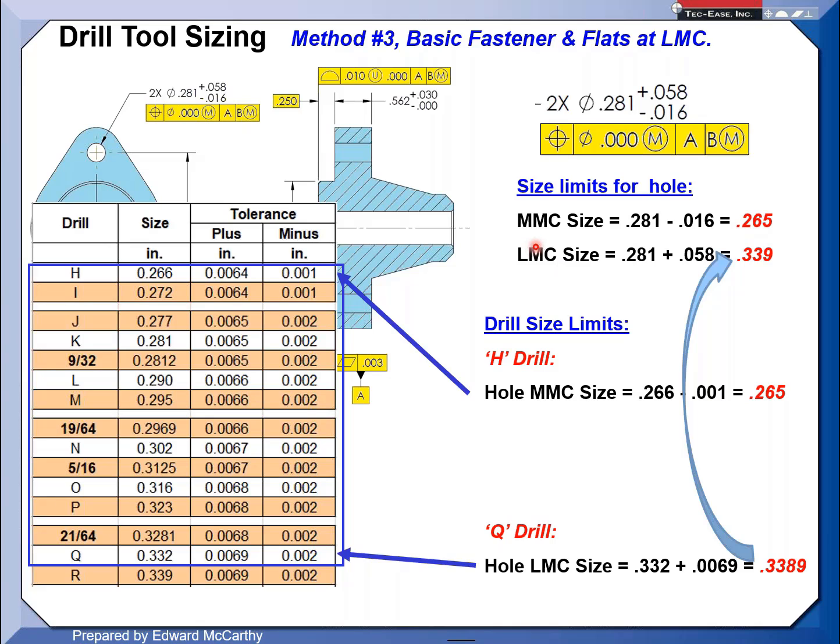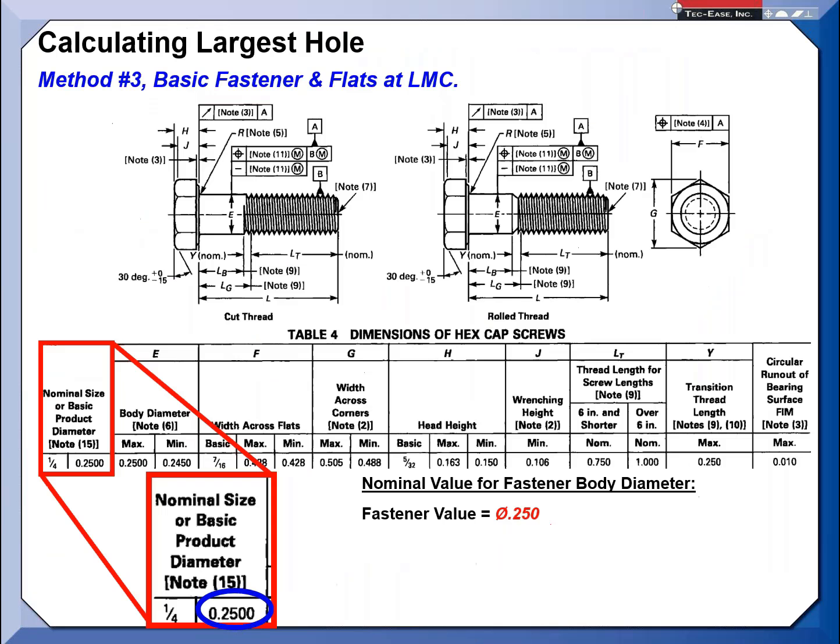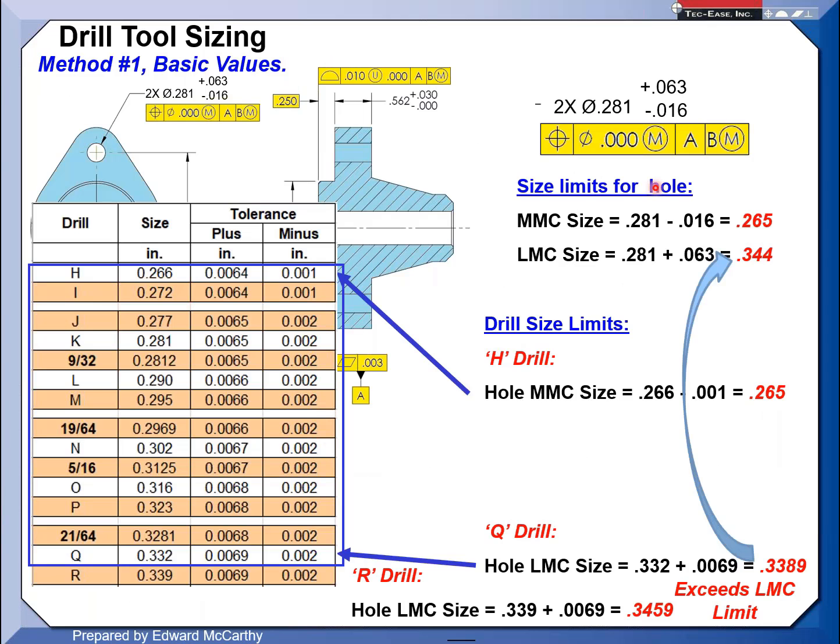Okay, Ed, I have someone who typed in a question. Why on method number 2 is the position error between the head of the bolt and the head of the body not taken into consideration? I have noticed that only the 0.241 diameter is used. We know that the bolt is centering on the pitch diameter and not on the major diameter, which is the value used.